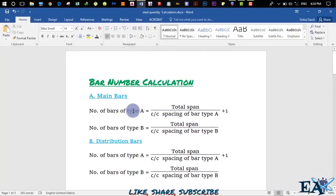Okay, so the number of bars of type A is the total span divided by the center to center spacing of bar type A, plus 1. And the number of bars of type B is equal to the total span, this is the same value, divided by the center to center spacing of bar type A, and here we don't do plus 1.